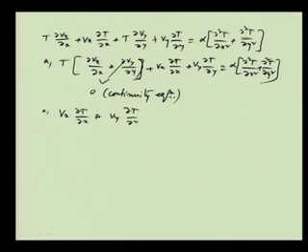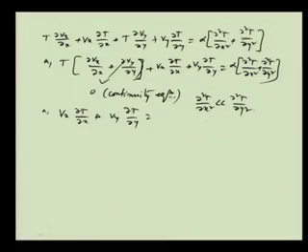now what we will do is that ∂²T/∂x² is much less than ∂²T/∂y². That means, the assumption is that the second derivative of the temperature in the longitudinal direction is much smaller than in the transverse direction. Based on that, this one is neglected because of that assumption. So, then we will write that it is alpha into ∂²T/∂y².